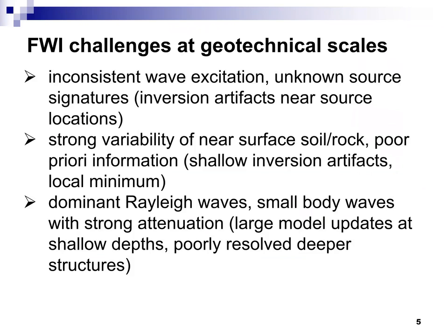If we don't address the challenges well, we don't get much of a result out of the full waveform inversion. It's just stuck at the first few meters of shallow depth. We cannot resolve deeper structure. So for seismic testing, if we use a sledgehammer to generate the wave field, the wave excitation is not consistent. We don't apply the same load at each source location. We don't measure the source signature.